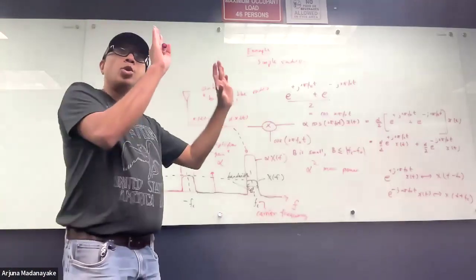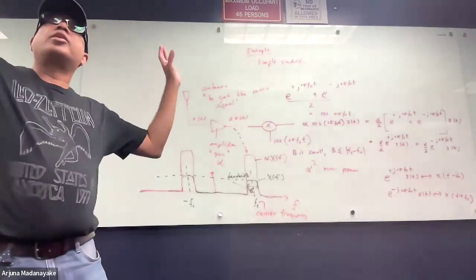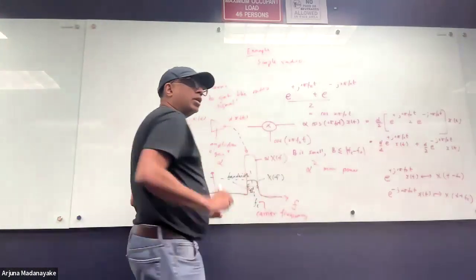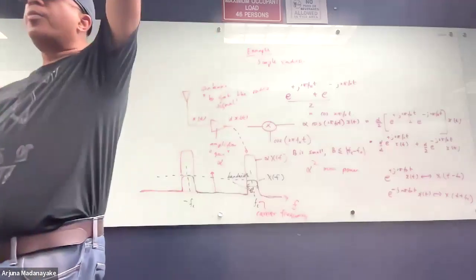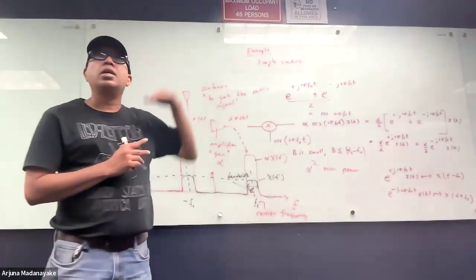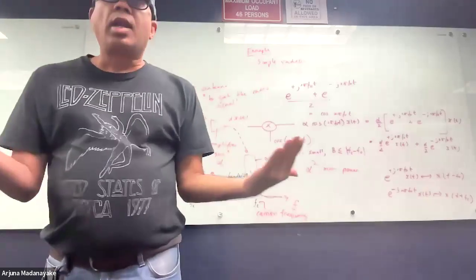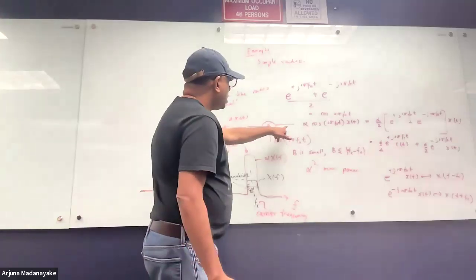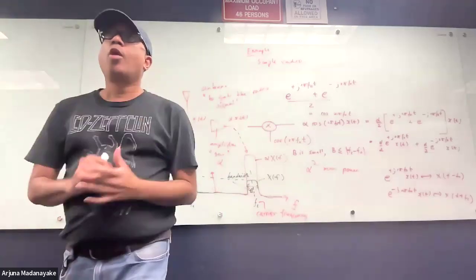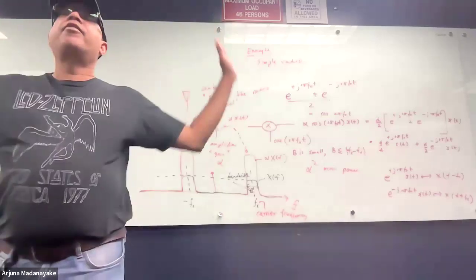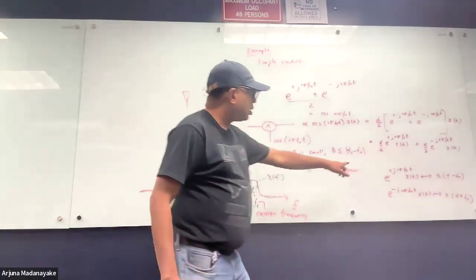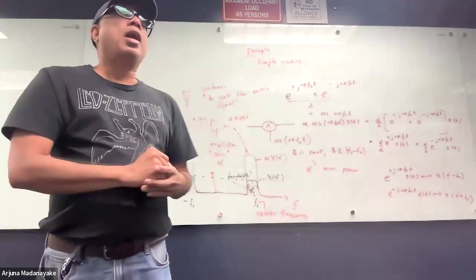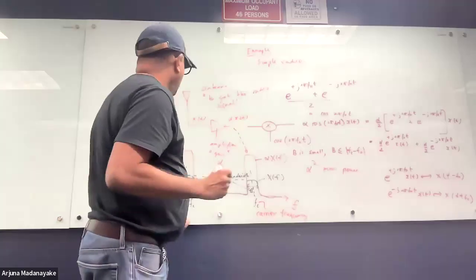The first copy is going to be shifted by f0 towards the positive end, and another part will be shifted down. It's up converted. You have one copy of the spectrum that's up converted, and another copy of the spectrum that's down converted. The final result at the end of the mixer is going to be two images of the original spectrum, one at a higher frequency, increased by f0, and another copy that is brought down by f0. So let's draw it.